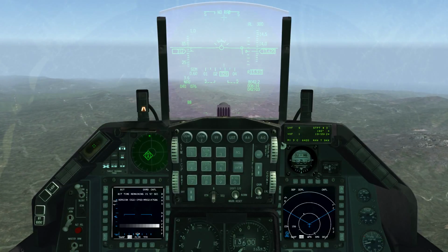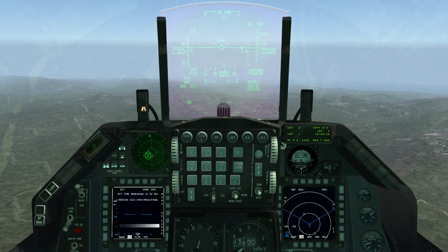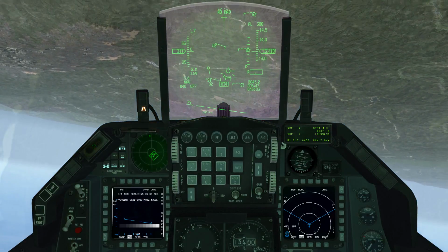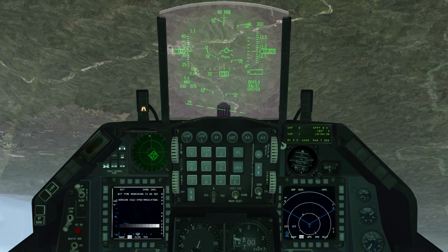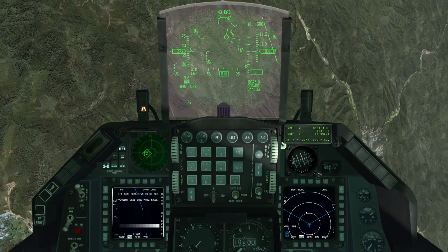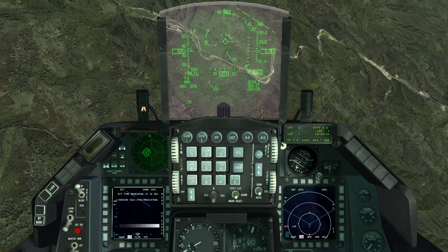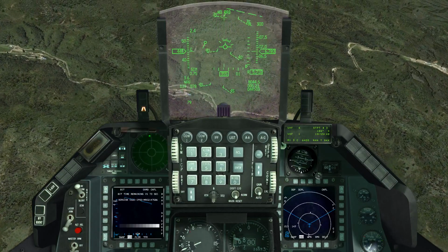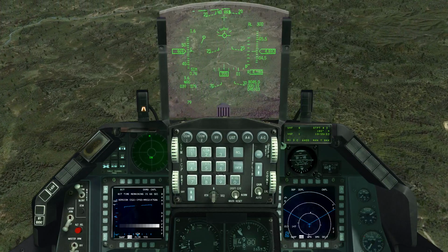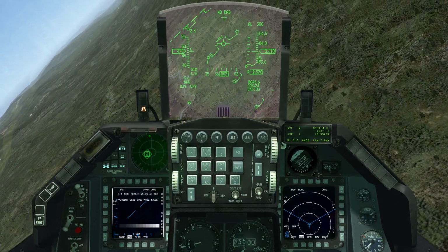Okay. The last consideration here, the last engine start that I want to do is at low altitude. So let's get down in the weeds here. And when you're at low altitude, you really don't have a lot of time to get the engine restarted before you hit the ground. So it's going to take 3,000 or 4,000 feet of altitude to get this engine restarted. So they suggest that as soon as possible, immediately you get the JFS switch going.